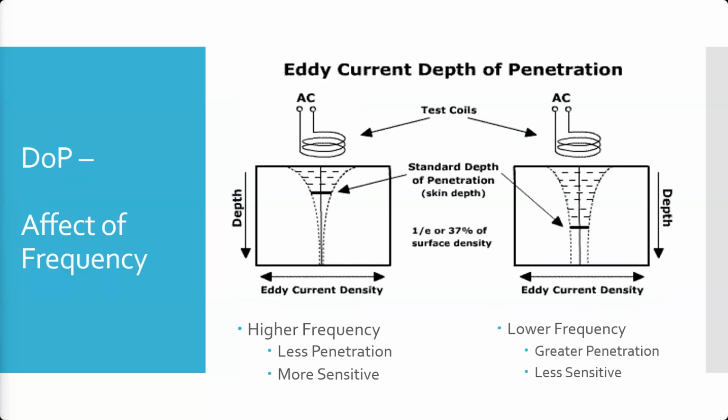If we need to find those deeper flaws, corrosion usually is visible, right? In most cases, before it becomes so bad that it causes a failure, usually it's visible. Cracks oftentimes can be so small they're not visible at the surface. The corrosion we're trying to find in a lap splice using eddy current testing, if we were to pull that apart, we'd probably be able to see it without a problem.